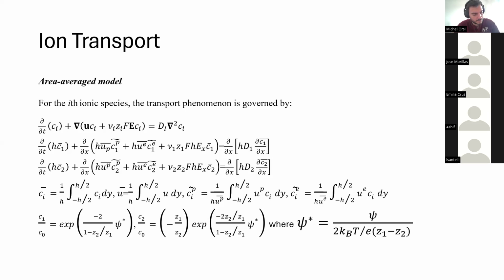For simplicity in the calculations, without compromising the central physical theme of our work, we consider a slit parallel plate microchannel for which the lateral width is much larger as compared to the depth of the plane of flow. Thus, the area averaging of the transport equation effectively concerns averaging over the channel depth. Accordingly, for each of these two ionic species, this equation may be integrated over the channel depth along the y direction to arrive at the area averaged forms, which are given by these two equations.